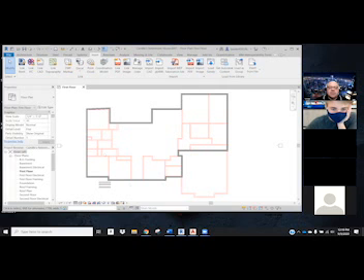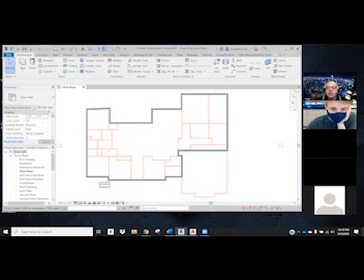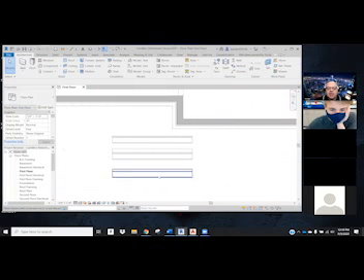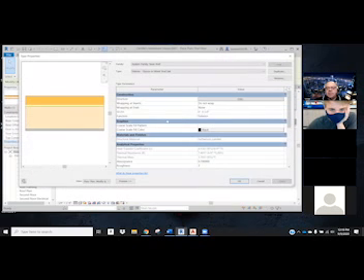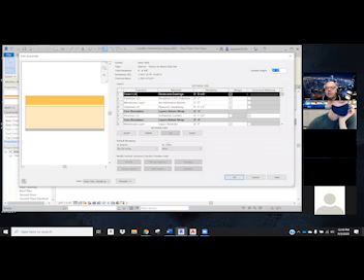Okay, Victor, I'm going to bring up those stucco wall settings again. So here's how I'm going to do that. I'm going to come right down here. This is the stucco wall. If I select that wall, then I can go to edit type and into here. There they are for you. So we've got a finish with 1/8 inch. We've got polystyrene insulation that's 2 inches, and if you want to make that thicker or thinner, that's your choice. You can do that. And then the rest of it should stay pretty much the way it is. You do have to add that in. Okay. Good question, though. I don't mind helping.